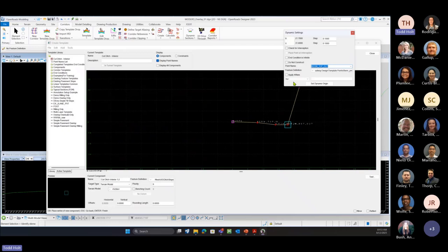This is going to be our HS, and this is where we're going to go 6 for a distance, and this is going to be our 1 and then semicolon 3. So we want 1 to 3 up. And we'll hit enter. And then from this point, we do want it to start solving. So we're going to check for intercept. We're going to place the point at intercept, and our end condition is infinite.